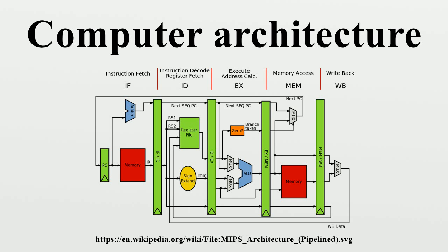There are two main types of speed: latency and throughput. Latency is the time between the start of a process and its completion. Throughput is the amount of work done per unit time. Interrupt latency is the guaranteed maximum response time of the system to an electronic event. Performance is affected by a very wide range of design choices. For example, pipelining a processor usually makes latency worse but makes throughput better. Computers that control machinery usually need low interrupt latencies.